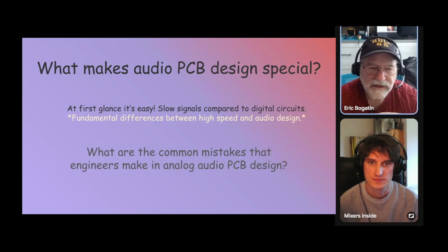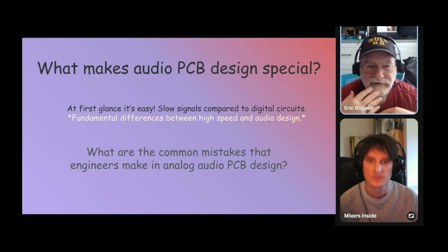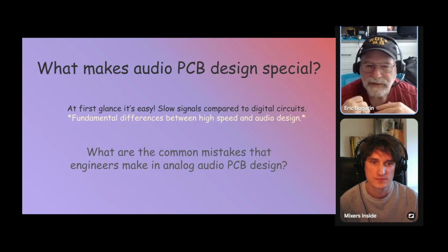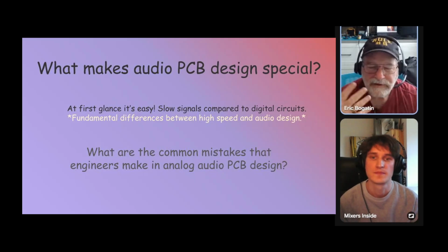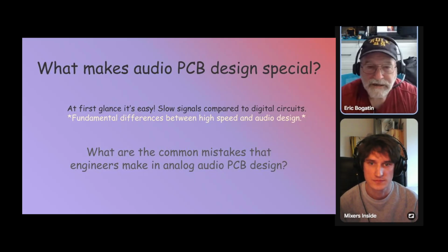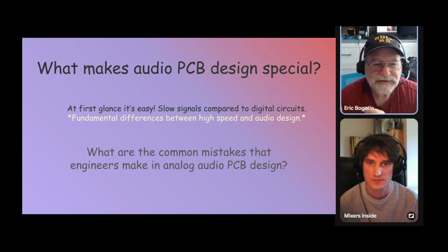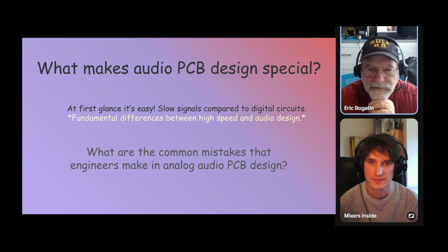And I think the other is that in audio you're dealing with really low signals. They're in the millivolt range. That means sources of noise that may be common in designs, in the millivolt range, are going to really degrade your signal's noise. So you have to pay attention to really small, subtle noise sources in audio design that are still there in high-speed design, but your signal levels are so much higher you don't care about them. So you have to pay extra attention to those small noise sources.